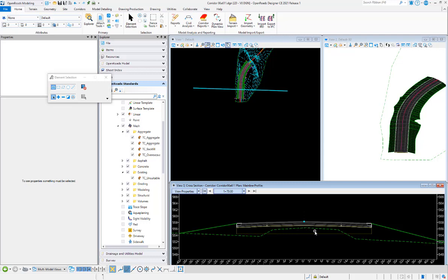That 2 feet, we want to quantify differently from what's just going to be filled under the structure there. So perhaps we're going to do some different compaction or some kind of treatment to this area, so we need to quantify it differently than what's just going in here fresh. And I think sometimes this is called moisture density control or over excavation with select bedding, those kinds of terms there.